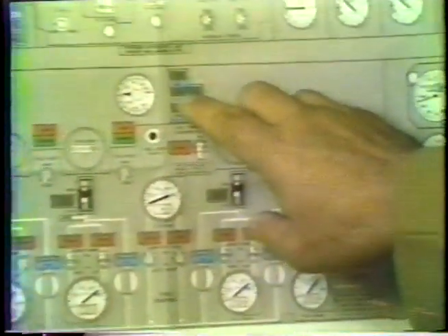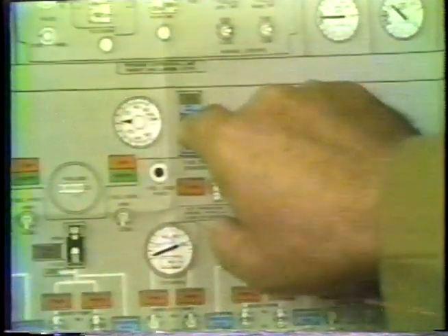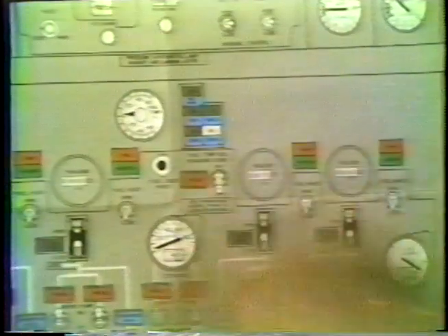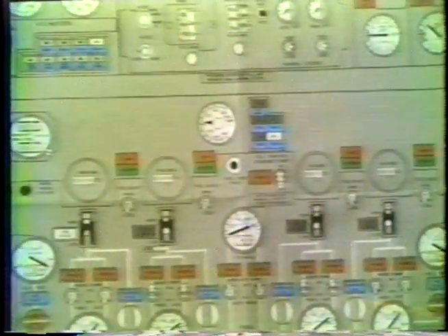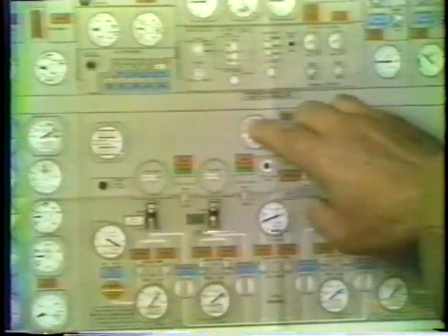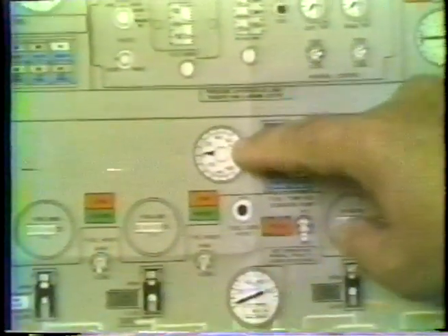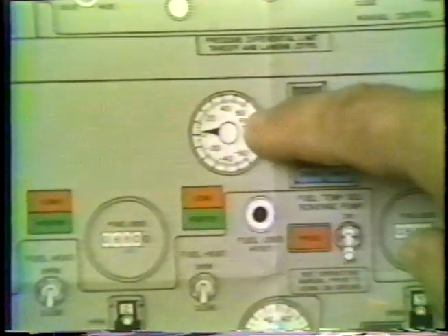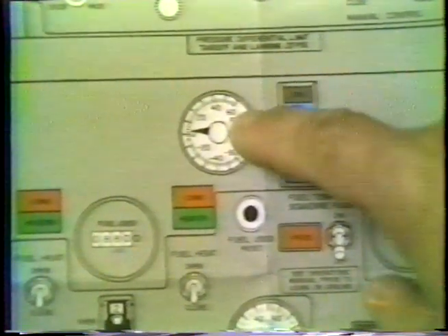Anytime you have abnormal oil temperature in the caution band, one of the first things to be considered would be to check that the fuel heat on that particular engine is off, and going to the fuel panel, making sure by selecting that engine what the fuel temperature is. The fuel temperature with fuel heat on will generally make the meter read at 60 degrees or higher. Pegs out the meter.